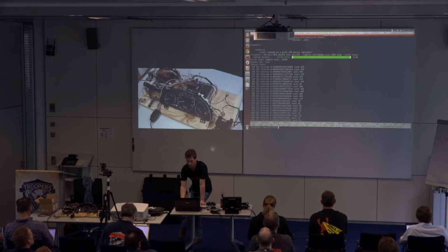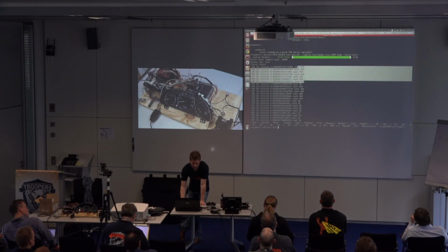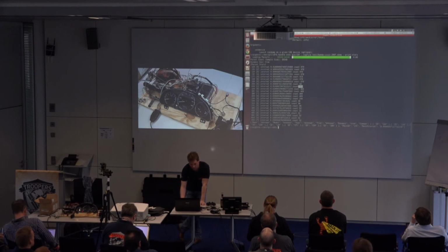So if you were targeting a vehicle, you know this vehicle is the one you want to look at. Here are your common IDs. Your main ID is 17C, and this is your main interval. It determines that by looking at your packet payload count here, and then your arbitration ID. By glancing at this you can see that, okay, this is a common one, a 978 with the sample size we had. Probably the next one is here.